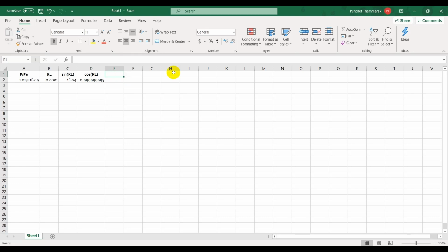Okay, so we look at the RA, which is equal to theta EI over L square multiplied by, in the bracket, KL square eta plus alpha beta over omega, etc. So let's start with eta.